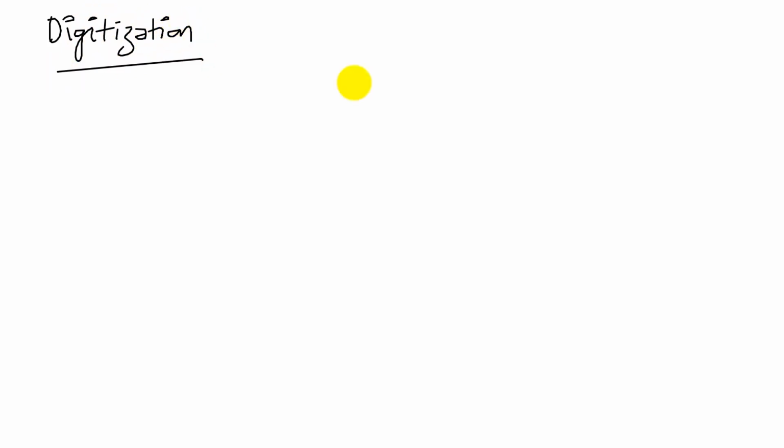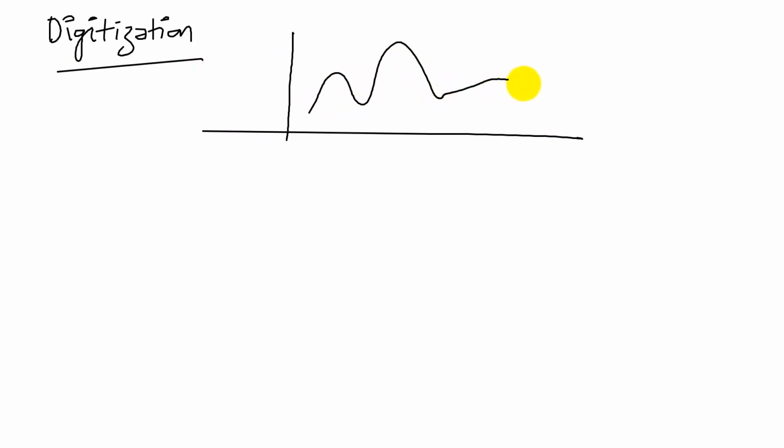So we saw that the purpose of digitization is to take an analog signal and digitize it, which means to store it in a computer. So we have an analog signal that's continuously varying in time, and for now we will think of it as a changing voltage, and we want to digitize this. So digitization is done using two concepts. One is our amplitude quantization.